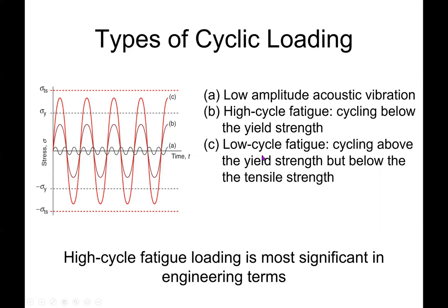So low cycle meaning that it only takes a few back and forth cycles of fatigue. This would be like bending of a paperclip, right? You bend it forward and back, and only after a few of these cycles, you get fracture. Okay, so that's not usually all that interesting either, because in this case, you're loading above the yield strength, so you've already exceeded a design limit anyway, and then you get fracture. So really not the best example of fatigue, but it's the one that people use a lot to explain fatigue.